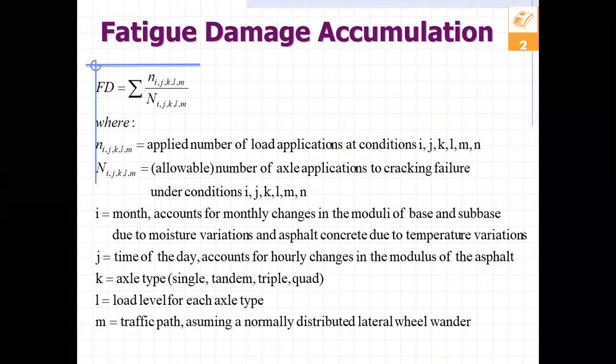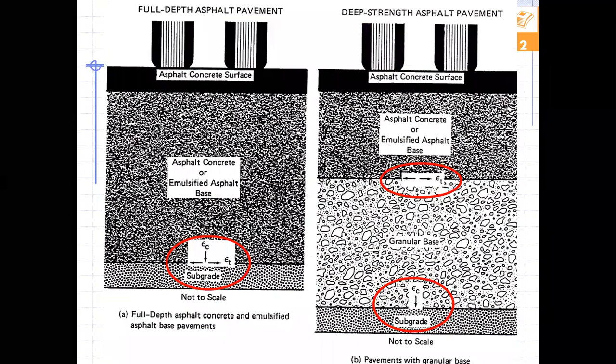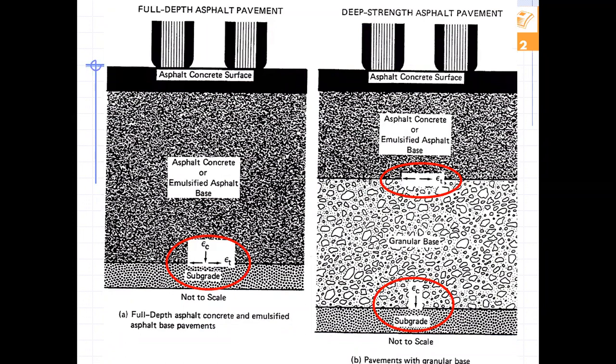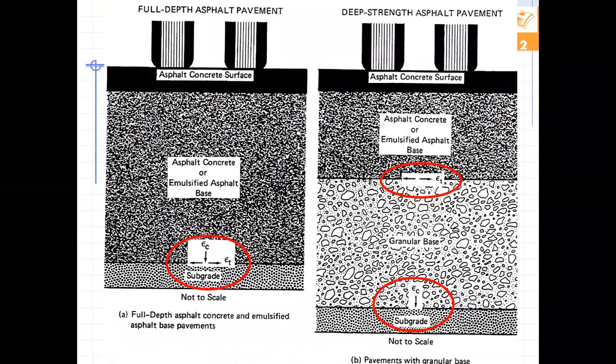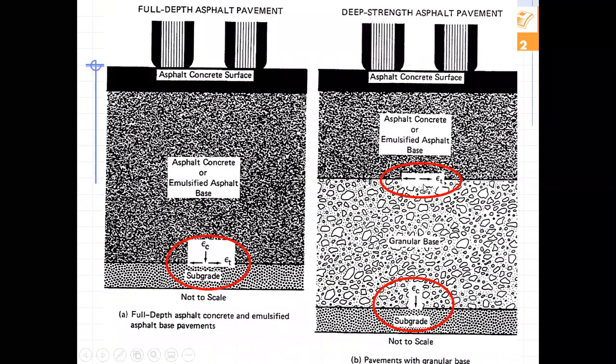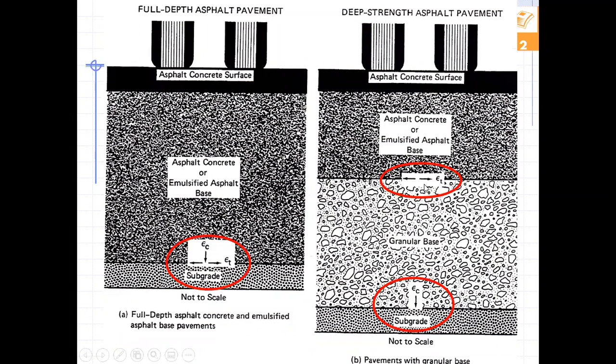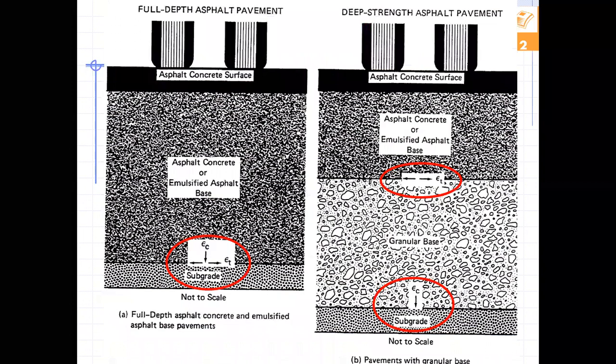Sometimes alligator cracks appear without any evidence of settlement, and it seems they are only due to the repetition of load. But there are some alligator cracks which form after the settlement of the pavement. Can we name these kinds of cracks fatigue cracks as well? They are fatigue cracks as well, but they are fatigue cracks combined with rut depth or rutting.